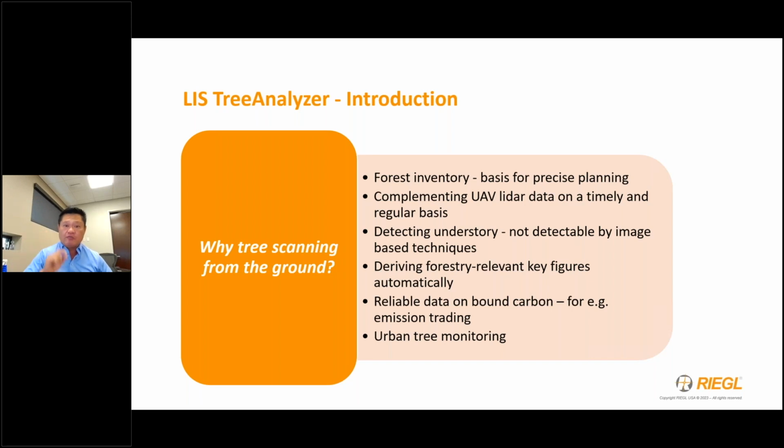Yeah, so there are different platforms, but more importantly, within our software products, from ALS, kinematic to static, we can do data fusion, we can merge the data together within our same platform. So you fly over an area with an unmanned system, you scan a plot, you can match that together pretty much automatically using plane-to-plane surface matching.